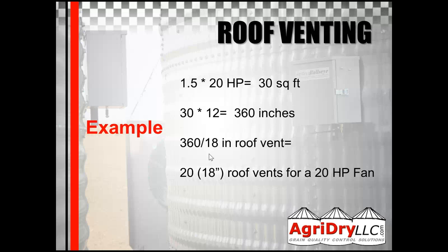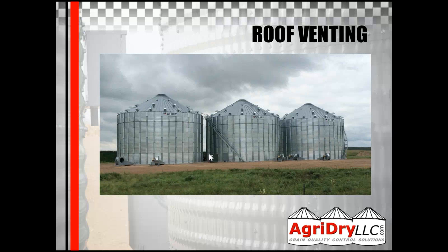But it's a quick way, I would say, to change your airflow just by adding more roof vents, which is then going to cut down on your static pressure, which is then going to give you more CFMs per bushel. It all ties together just by doing that type of simulation.